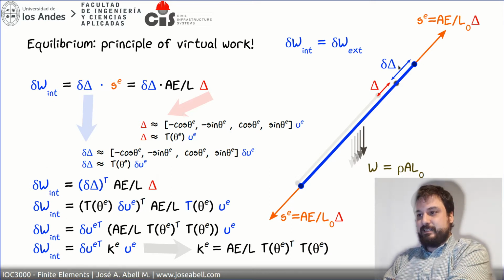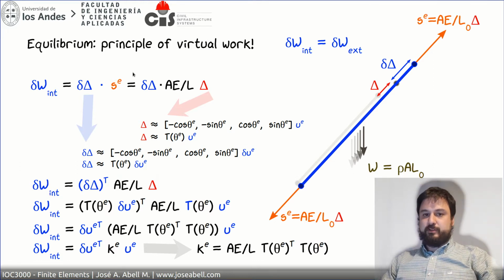So this delta is a virtual stretching on top of the original stretching that we're applying for the principle of virtual work. And we multiply that by the equilibrium forces of the element. So we plug that into the equation.